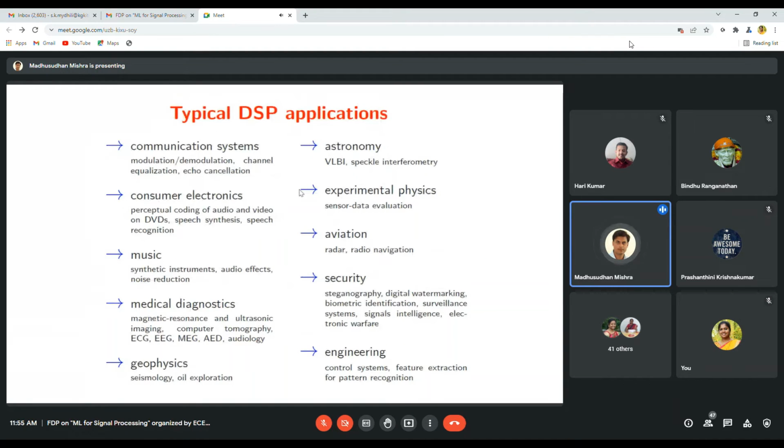Though there are many advantages of digital signal processing over analog signal processing, there are certain areas where analog signal processing is used. For example, when we need to handle very high bandwidth signals, we always prefer analog signal processing, because there is no need to convert analog into digital, and after processing it doesn't require an additional digital to analog converter circuit.